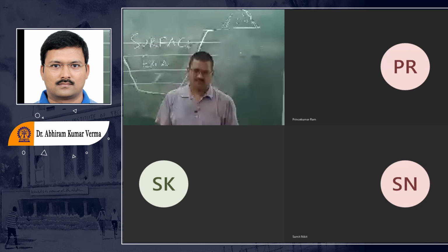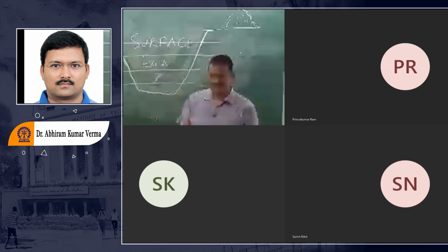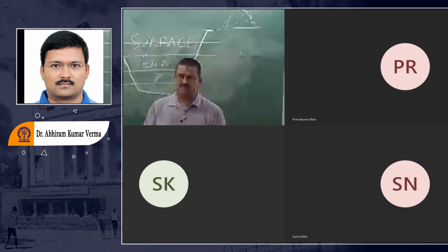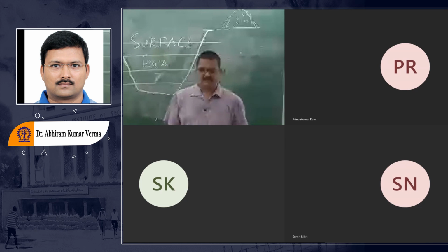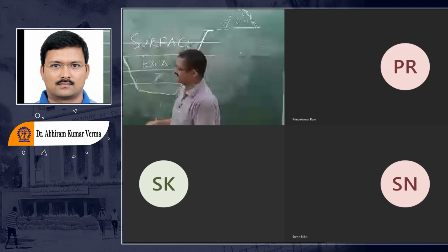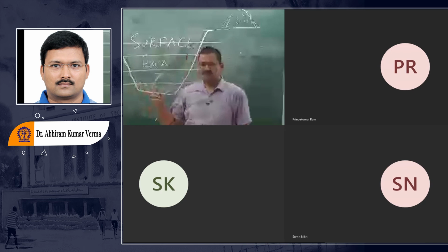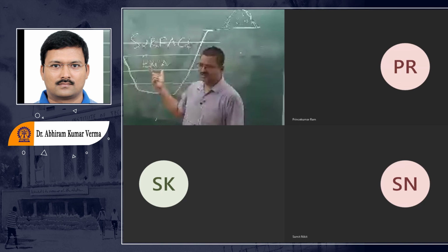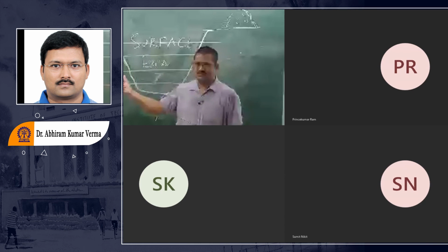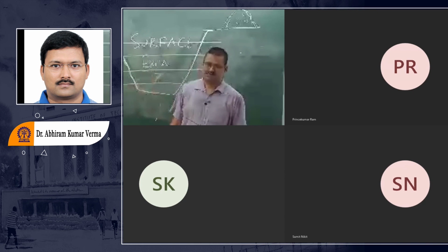So we have to be very, very cautious when such excavations already exist and we are trying to make another excavation side by side. We have to determine the safe distance between the two excavations, so that the second excavation is not affected by the first excavation.